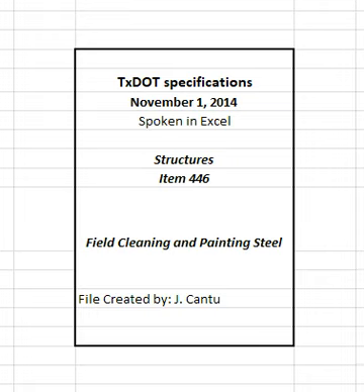Use an abrasive recycling system with an approved recyclable abrasive when abrasive blast cleaning is used to remove existing paint containing lead or chromium. Abrasive will be considered recyclable if it is separated from the dust and paint debris before being reused. All abrasives must meet SSPC AB 1, AB 2, or AB 3 as appropriate.